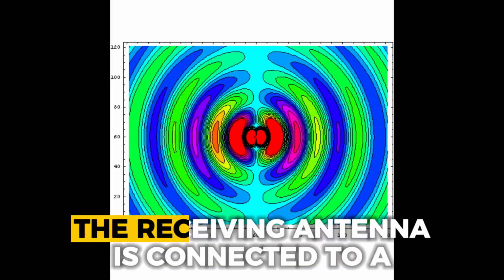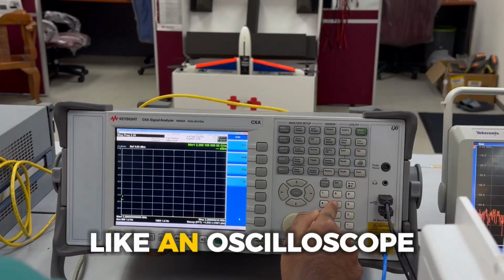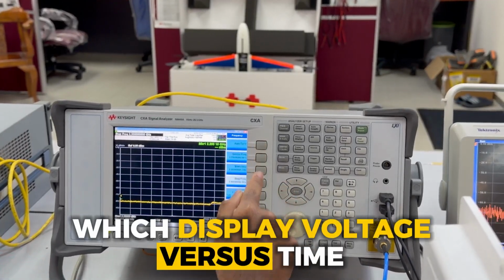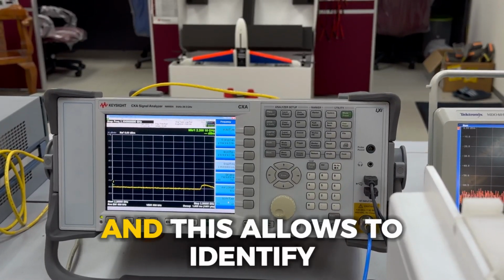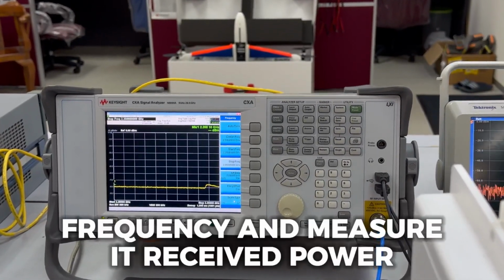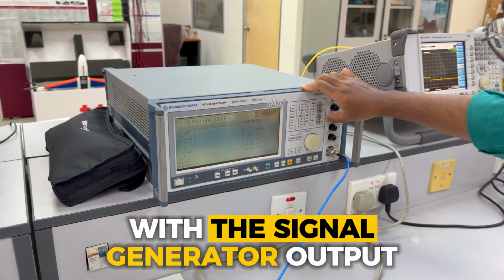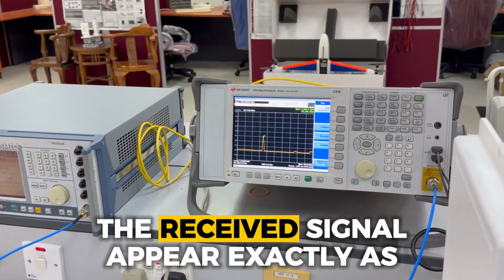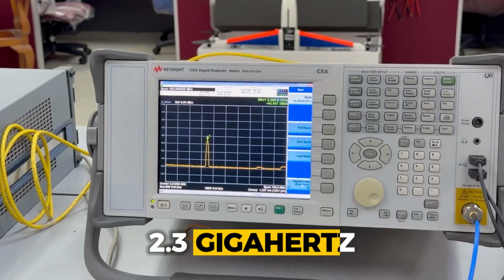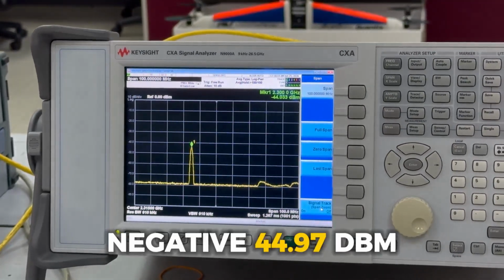taken in the near field. The receiving antenna is connected to a Keysight spectrum analyzer. Unlike an oscilloscope, which displays voltage versus time, a spectrum analyzer displays signal power versus frequency, and this allows us to identify the transmitted frequency and measure its received power level. The first transmission is performed with the signal generator output set to -20 dBm. On the spectrum analyzer, the received signal appears exactly at 2.3 GHz, while the measured power is approximately -44.97 dBm.